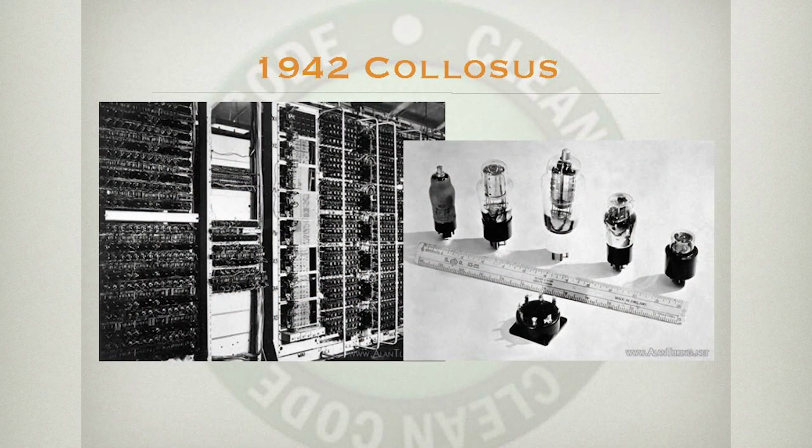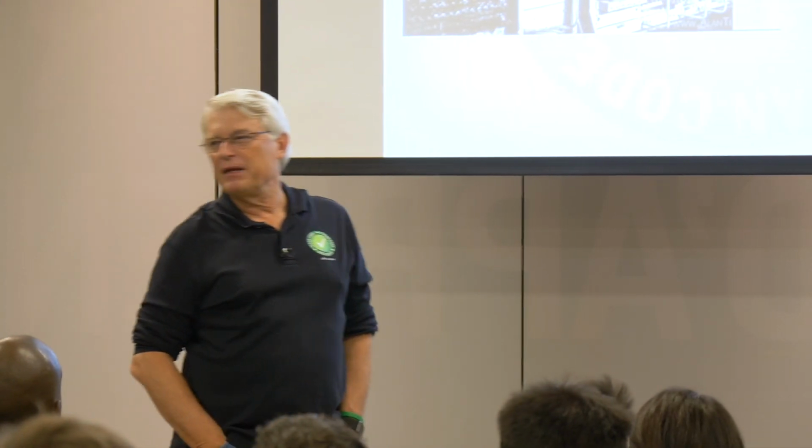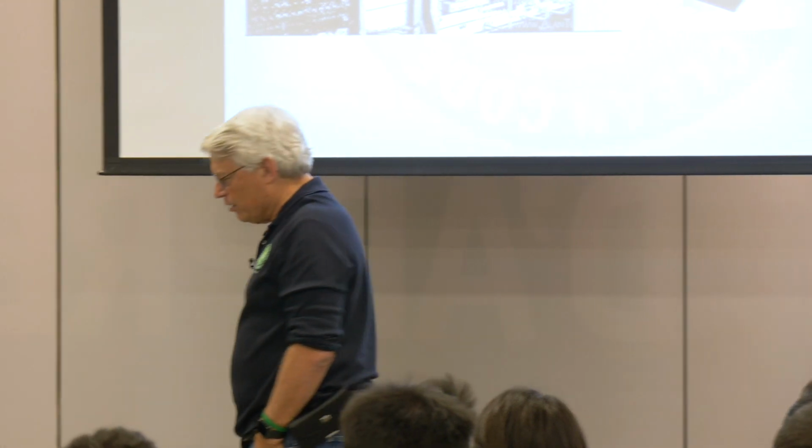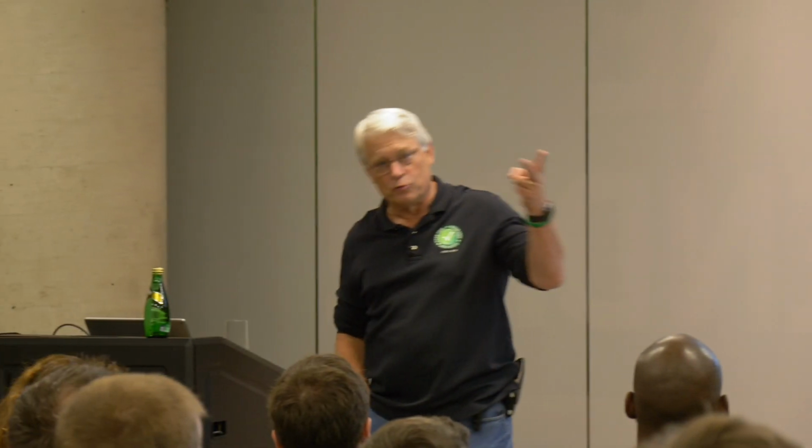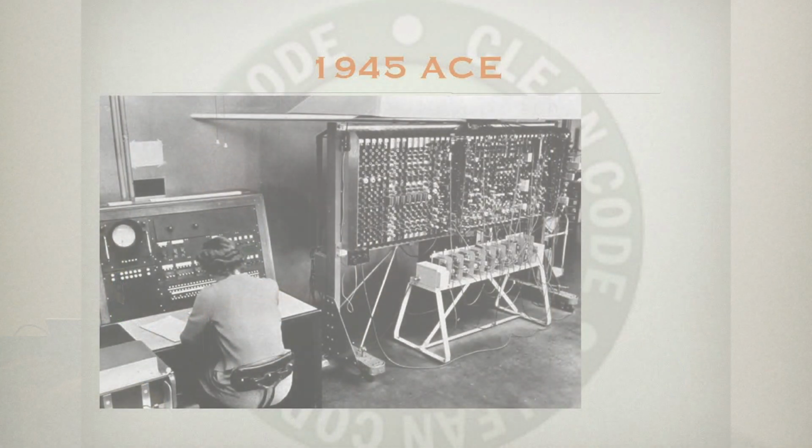Vacuum tubes had been invented, and they thought about using them. A vacuum tube would be 100,000 times faster. But they were really unreliable in those days. They weren't being mass-produced in any quantity. They weren't being reliably produced. They drew a lot of power. They failed a lot. They leaked a lot. So they couldn't make anything very reliable out of vacuum tubes. A vacuum tube could be used reliably in a circuit that had 1 or 2 tubes in it. But if you had to put 100 tubes in it, you knew that they were going to fail. So they didn't want to do that until a little later.